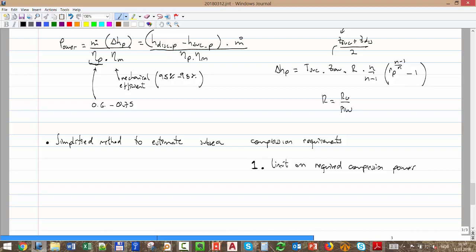We don't have too many Subsea compressors, but that limit per unit currently on the market is something around, actually it's the Oscar, 11.5 megawatts per unit. That tells you the current limit. That might change. Maybe in a few years you see this lecture becomes obsolete, but that's the current limit. The biggest machine they can build is 11.5.